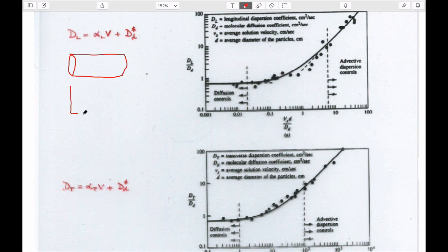We know that flow along that sample would look something like this, if this is the length and this is the concentration. If we physically drew what that looked like, it would look like these fingers of solute going down here, so that on average, not DNAPL lenses, but on average the concentration, if you averaged it over this whole thing, where you have some fast flow path fingers, some slow flow path fingers, the concentration would look like this here.